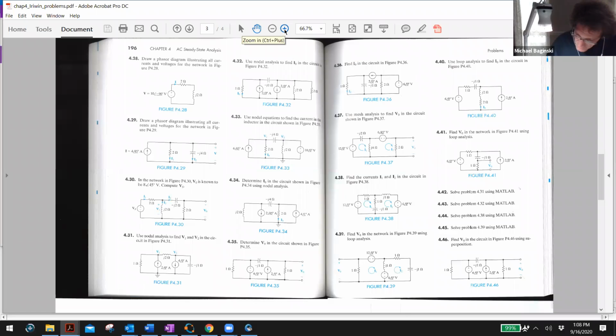and then it has a voltage source. I got a comment about this one. And it has 10 at an angle of 0 degrees. And it says use nodal. Now here he puts in a ground. Not all the time is that shown. And a ground means what, anybody? Voltage is 0. Yeah, the voltage is set to 0. It's the reference voltage, right? Every voltage is measured with respect to that, correct, class?